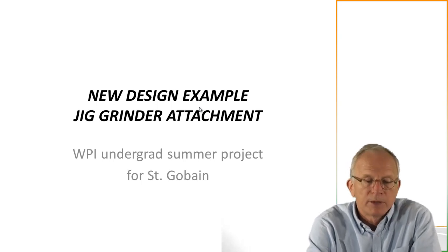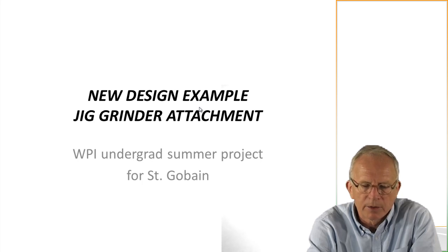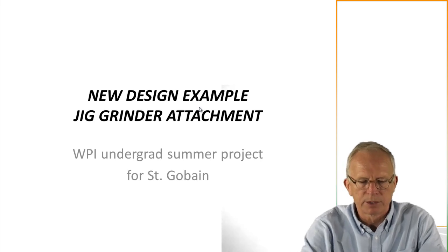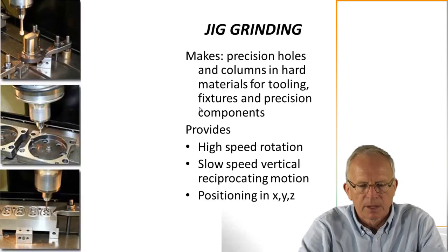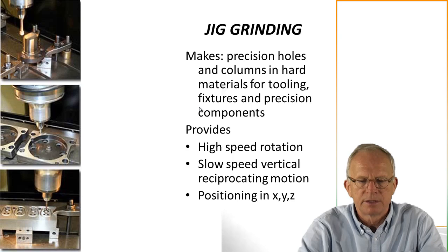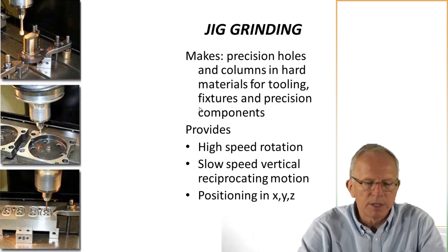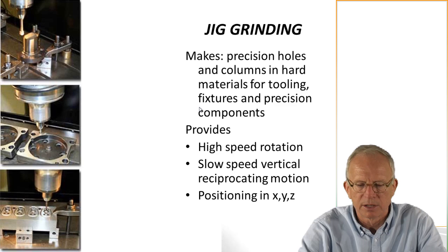We looked at this briefly in a previous module, and this is the jig grinder. Now, this was a WPI undergrad summer project from Saint-Gobain here in Worcester. And the customer need is to make precision holes in hard materials for tooling, fixtures, and precision components. So we need to provide high-speed rotation, slow-speed vertical reciprocal motion, and positioning in X, Y, and Z.